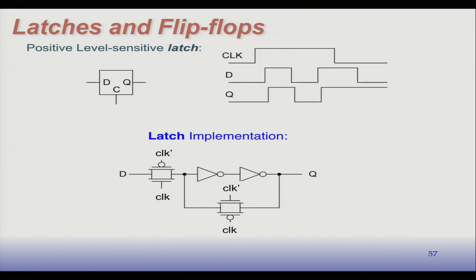And that's what we have there. The only question is, how do we change its value? We put those transmission gates in there to allow us a way to make it level sensitive, sensitive to the clock. Right. So what this says is, when the clock is high, we allow a new value to come into here, and we turn off the feedback. By turning off the feedback, it's essentially breaking this line there.